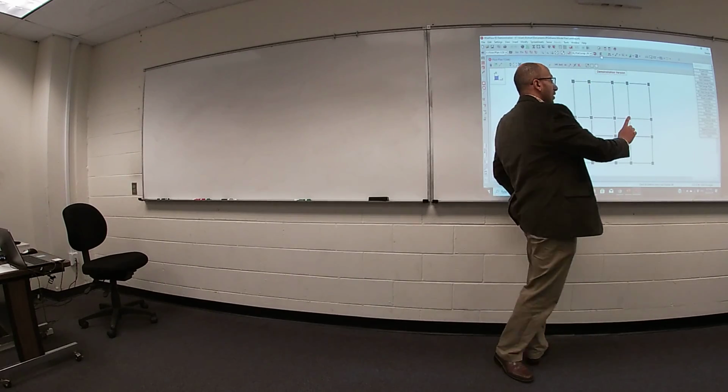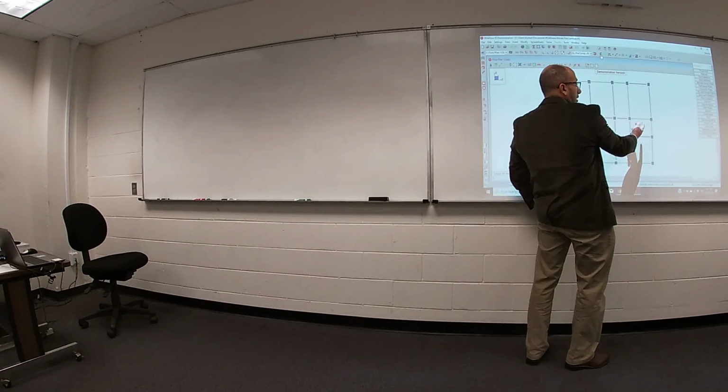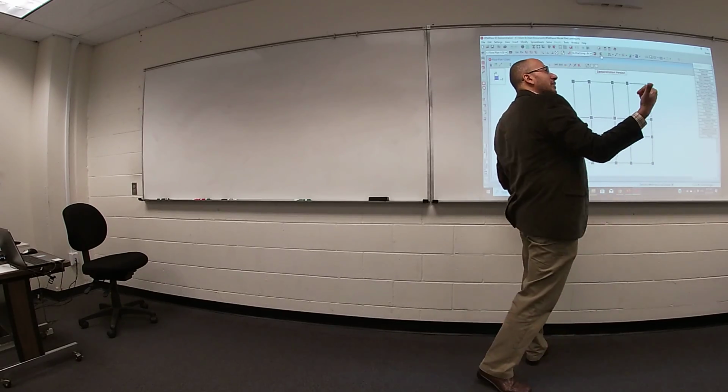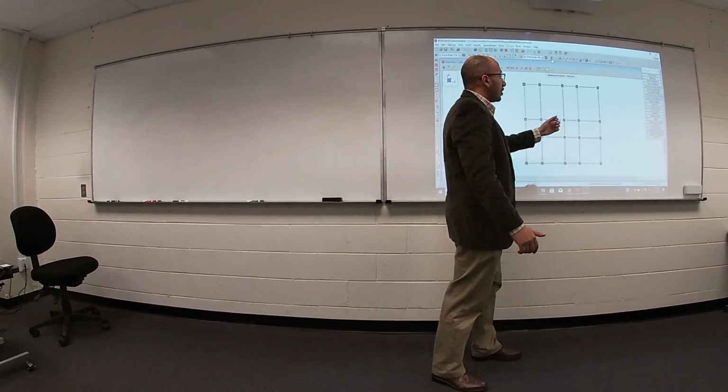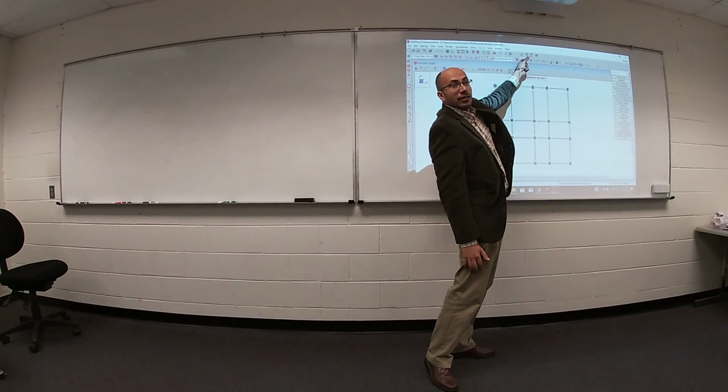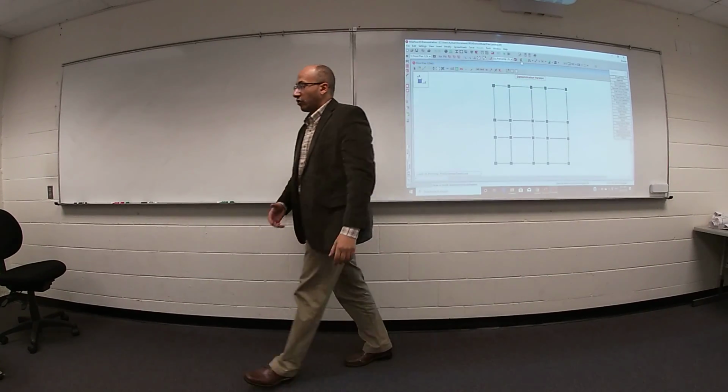So I'm confused. Do you have a beam here or not? I have only one line. Is this edge for a slab or this edge for a beam? To check, go ahead and use extrude view to make sure everything is drawn.